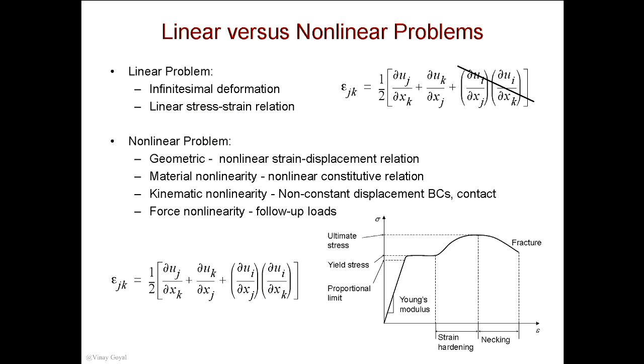But if now you have a stress that's 5 times the ultimate strength of the material, maybe you want to switch to the full stress-strain curve and do a nonlinear analysis, which is what this is here. So in a nonlinear problem, the strains can be very large, and you may want to consider them. Buckling is an example. The buckling problem you guys are working on is a nonlinear problem because you're going to have high deformations in that wall that have to be considered.